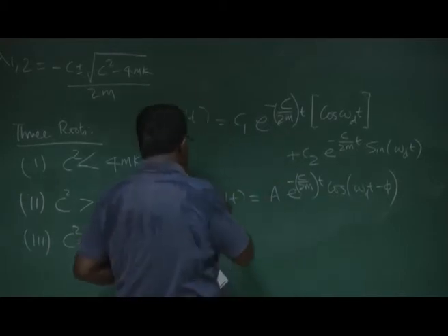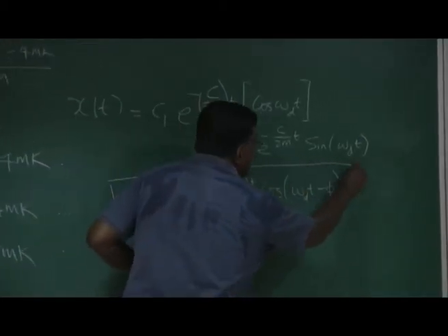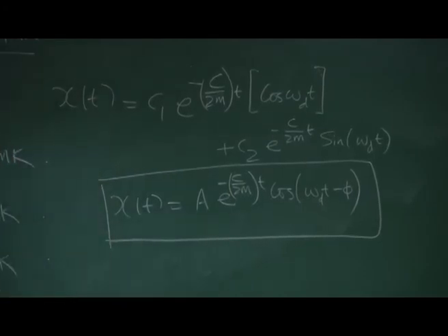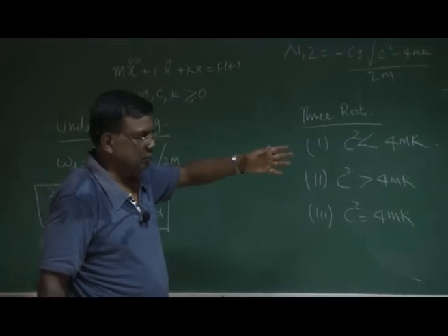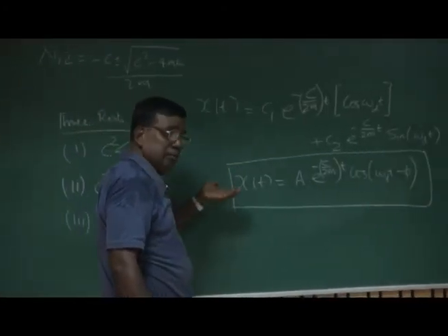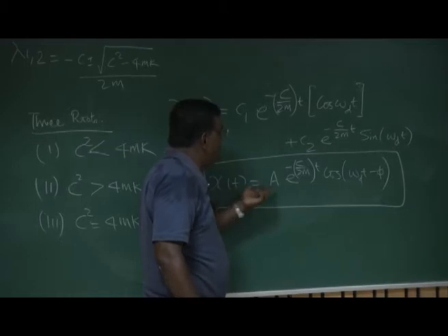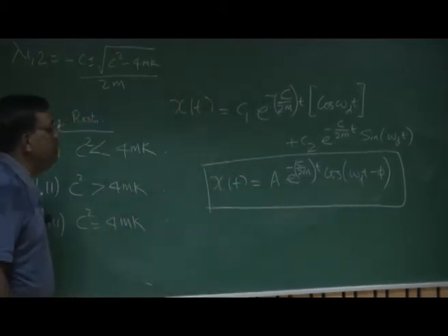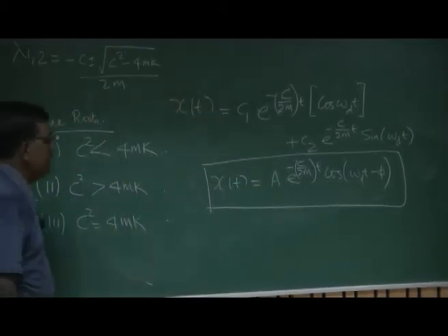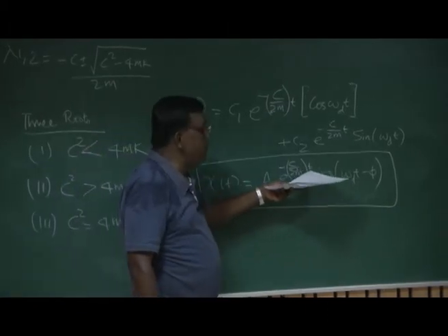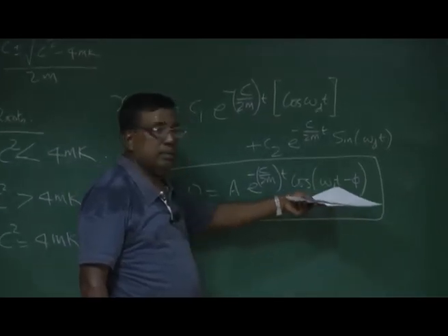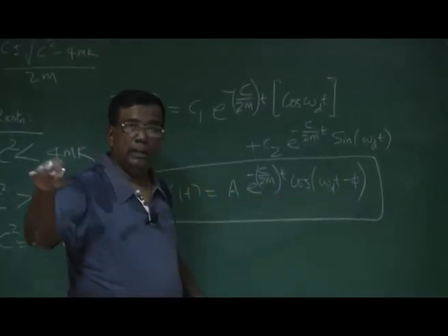But try to understand this. You do not require more than this mathematics to understand. One Laplace transform will be required, which is also very simple for our purpose. So these are our standard things. Do not get nauseated by what this expression is. Understand this. What is this expression telling you? It tells you x of t, the perturbed quantity, will vary with e to the power minus c by 2m t times sine and cos function. So it is oscillatory like this.